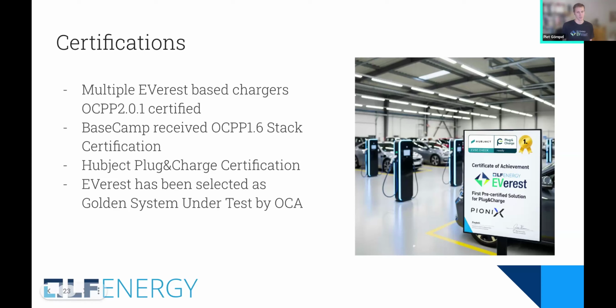And what else is great news is that EVerest has been selected as a golden system under test by the OCA, which means that EVerest will be continuously tested by the team that is developing the testing tool for OCPP, which is called OCTT. And this continuous testing definitely helps the project, of course, because it also ensures future OCPP compliance in a way.